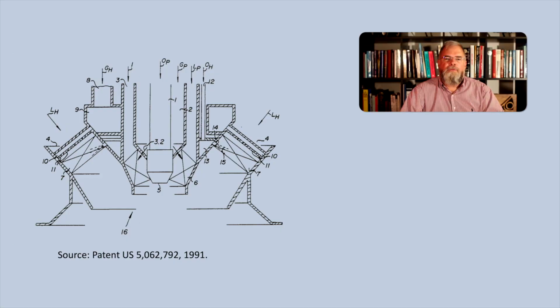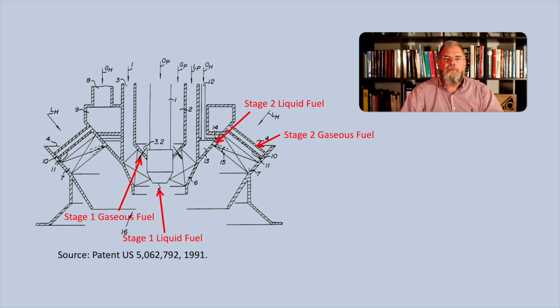Also in 1993, Siemens introduced their first premix burner, known as the hybrid burner, which saw service in a V94.2 engine in Sweden. This burner works on the principle of radial staging, with two independent swirlers and separate fuel feeds for both. Unlike ABB's burner, this burner has a premix mode for liquid fuel, where the liquid fuel under premixed operation is injected from the sidewall of the outer swirler.